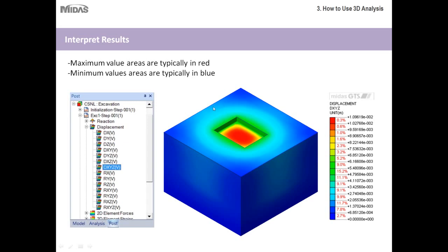And as you go further and further away from the excavation site, the displacement becomes less, up to the point where it's almost negligible. And that's what I was talking about with boundary conditions. For example, if I were to make my model too small, if I were to put the edge along here, then there'd be strain going past that point that I would want to account for, and I would want to make my model bigger. As you can see, the model is big enough, so all the strains and displacements are within that range.